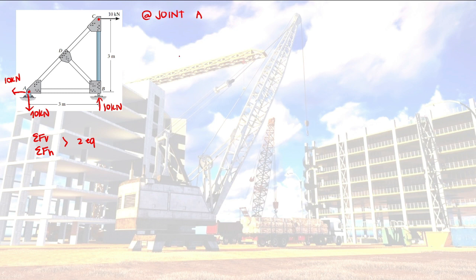A. So at joint A, let's draw our free body diagram. So this is our joint A. We have our reaction here, 10 kilonewton. Then we have here, 10 kilonewton. Then our member here, this is AB. Then we have a member here, AD. After this one, we already have the free body diagram. The next step is to do the components. So, let's define the slope triangle first.